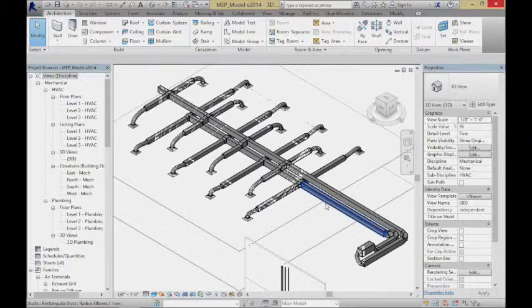Okay, and that actually solves some of your problem because you don't have to squeeze it in such a narrow space. It sounds odd, but it's a little bit more expensive to run the ductwork all open that way, because you have to do a very good job of keeping it all clean and looking nice if it's all going to be exposed architecturally. But one thing is, we'll just have an open system. And in some ways, that's really simple.